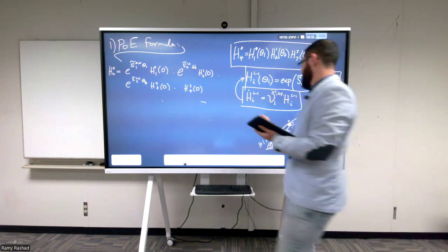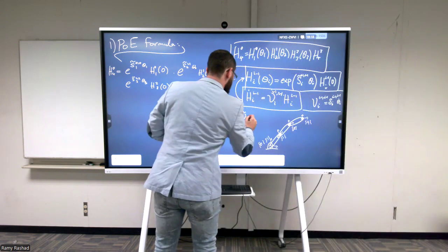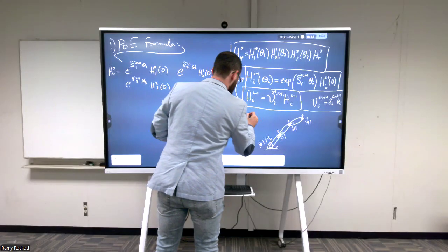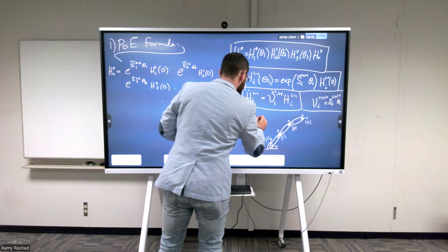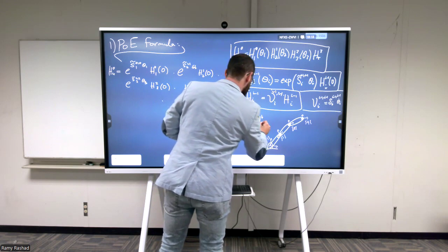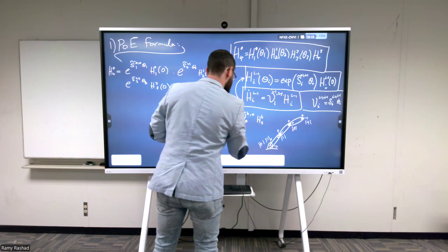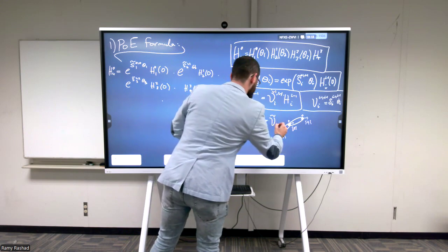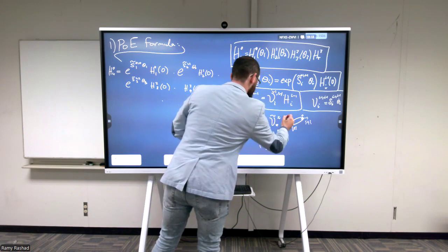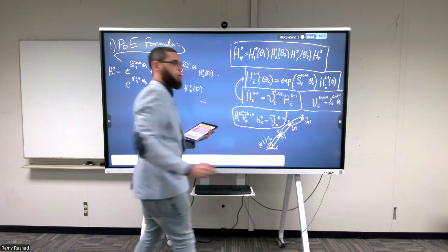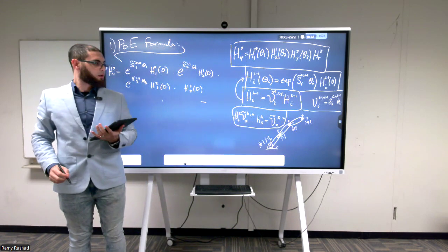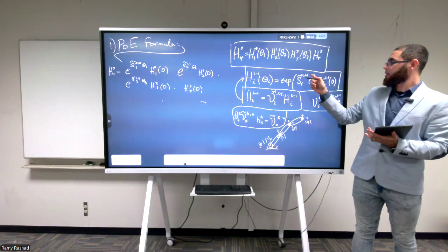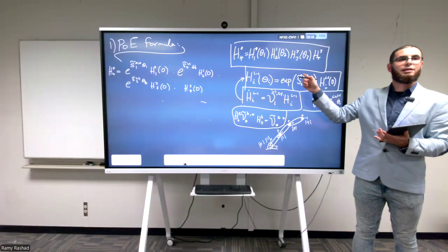If we have a twist between any frames, but expressed in, let's say, frame B, and then I have H SB and H BS, what is the resultant of this? This was equal to the V tilde in the S frame. You should have calculated this and proved it yourself in the assignment. So if we do this trick here, we're going to be changing where this twist is represented.